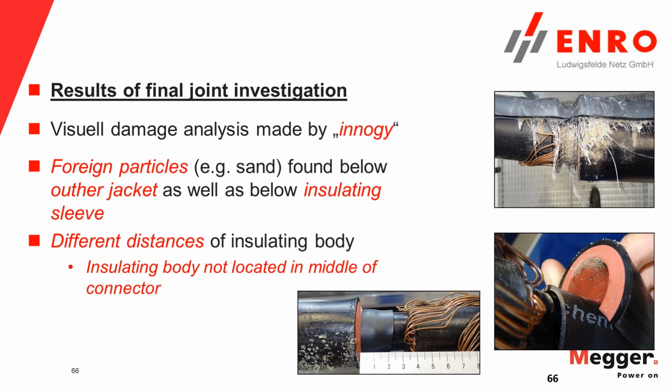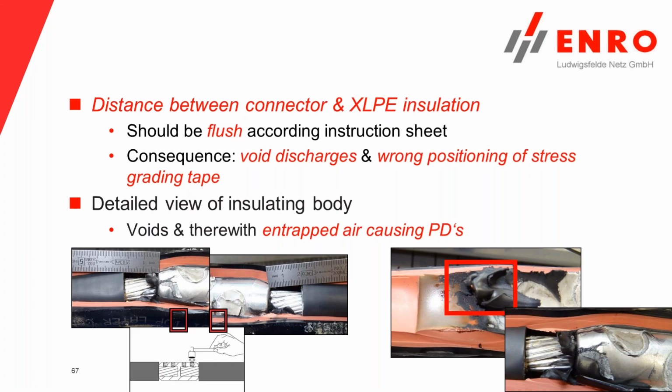I just wanted to show you the latest results. That is what I got back from our field test engineer that keeps track of that case. And he said, hey, look at this, they found this. So problems, definitely workmanship issues. And then they cut it open. So you see the analysis, and you see it should be a flush interface kind of, and you have all voids all over the place, and an incorrect positioning of the stress cone or the stress element. And so you were entrapping a gas inside a void surrounded by solid material, and that caused partial discharges.